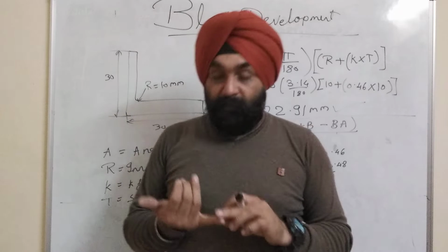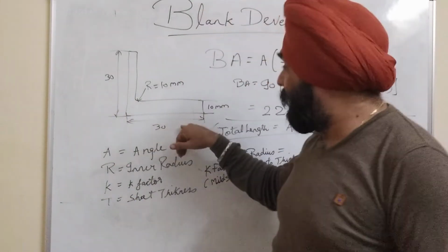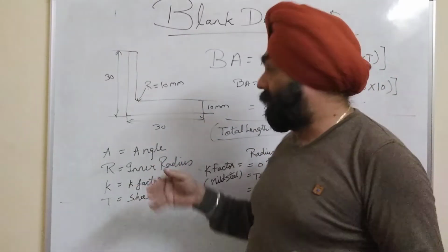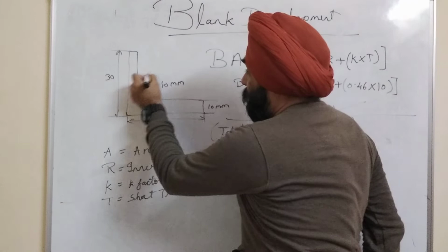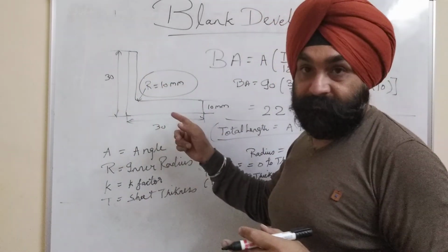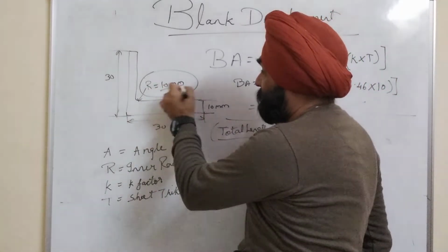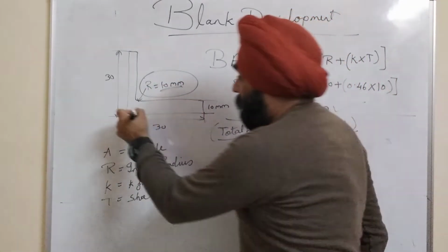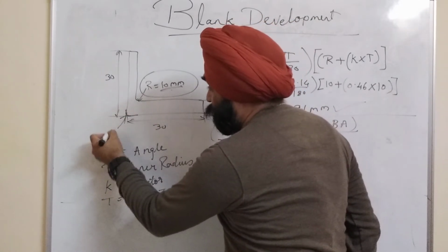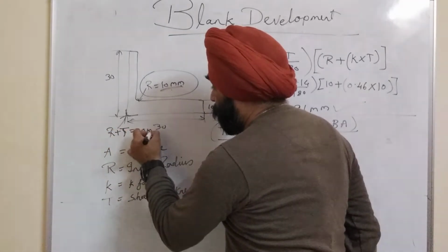Okay. Remember guys, also if you are into product design and you are designing something that is a bending tool or bending part, always think that this R is never less than your sheet thickness. And the outer radius is always added one sheet thickness, so R plus sheet thickness, that is 20 mm.